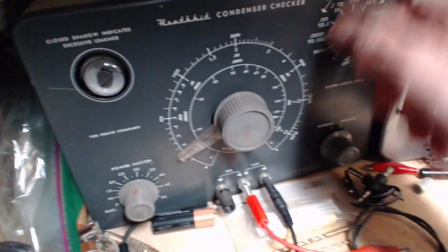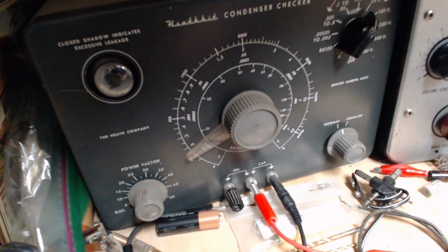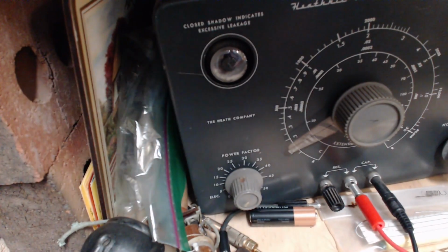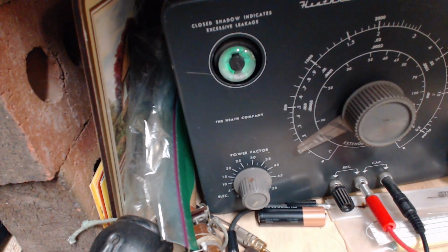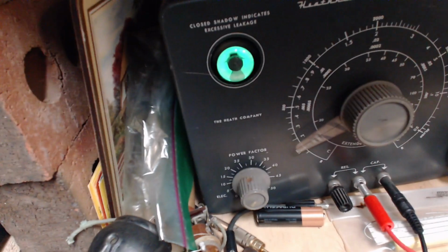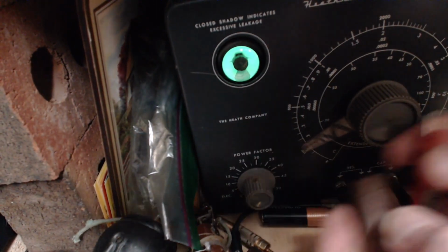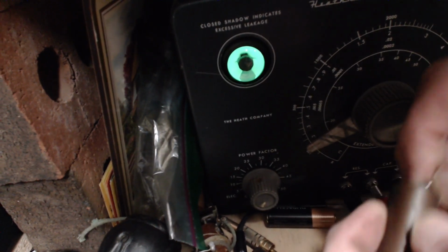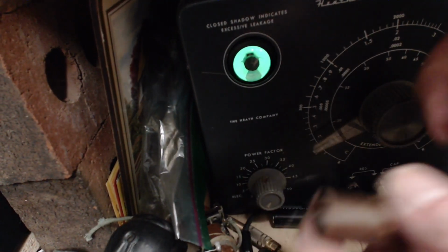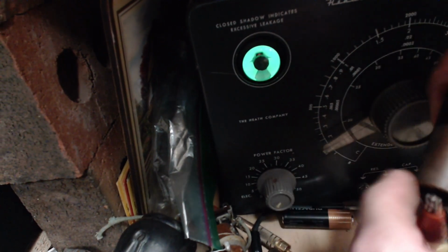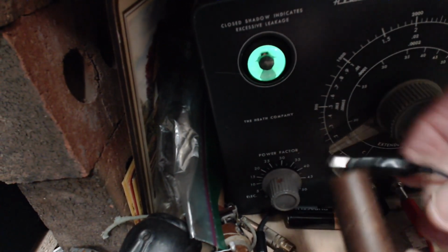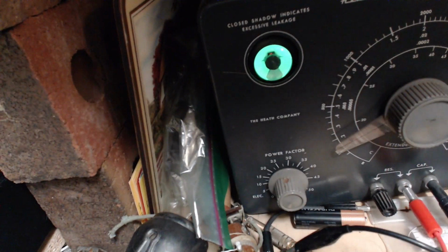Another 0.25 I have to find. And the screen circuits have high voltage on them, so it's got to be a good capacitor. Maybe I have to put a couple in to get up to this. 0.25. Now, I think screen circuits have a lot of current available, so a leak isn't all that critical.